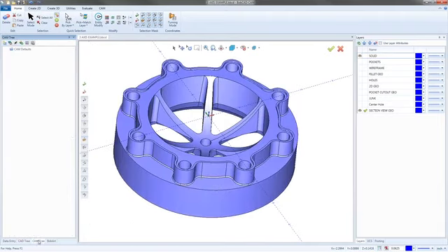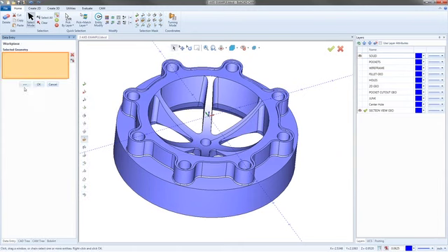So I'm going to go over to my CAM tree, and I'm going to right-click on my CAM defaults, and I'm going to start with a new job. I'm going to do milling. I'm going to use my BC3X mill, and for here, I'm going to go right into the stock wizard. So into the stock wizard.